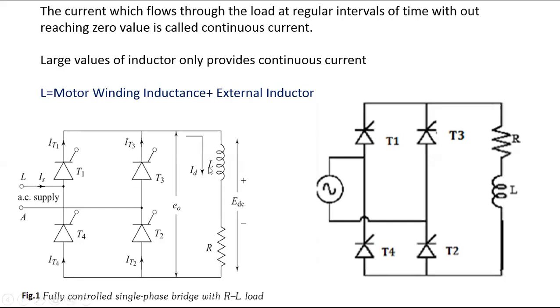So at omega t equal to 30 degrees, the inductor starts to energize. At omega t is equal to 180 degrees, case 2. What's going to happen at 180 degrees? At omega t is equal to 180 degrees, the current flowing through the inductor becomes maximum. It reaches the maximum value, but the input voltage and output voltage will become 0. Since the inductor cannot release the stored energy instantly, the current flowing through the inductor is maximum.